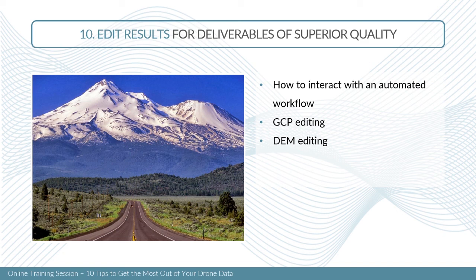For example, you want to remove trees, flatten out a surface, or flatten out a body of water. All these tools you can use to reach a better elevation model before you do the mosaic or the ortho, because bear in mind that the ortho rectification is very dependent on the quality of the elevation model.